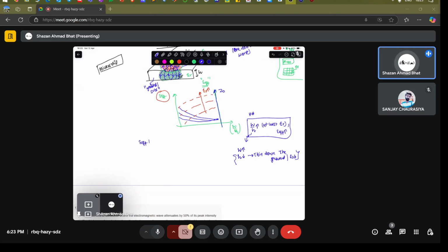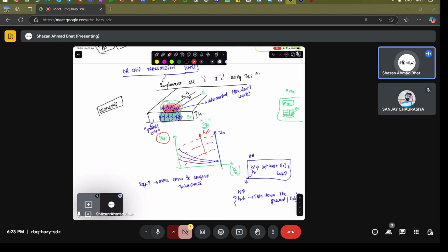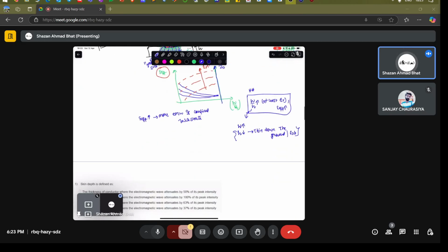So if epsilon effective is more, that means more of the electromagnetic wave is confined to the substrate. Okay, that means the leaky component which is in the air, which is this component, reduces. That's what we want. And the characteristic impedance reduces, and this all happens if you go on increasing this particular ratio. So that's why in terms of fabrication, people tend to iterate and thin down the substrate most of the time in order to see how this electric field profile can be tuned.